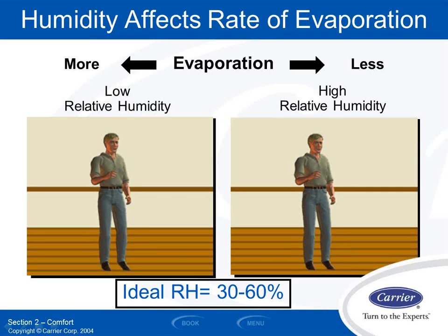Ideally, our humidity target is typically on the low end, like 20-30%. On the high end, it's 60%. ASHRAE standard 55, which is the ASHRAE standard for human thermal comfort, does dictate specifically a maximum indoor humidity of 60%. It used to have a minimum of 30% in the standard. That was removed from the standard, I think, in 2004. There is no minimum listed anymore, but the old minimum was basically 30%. So that's still a target range.